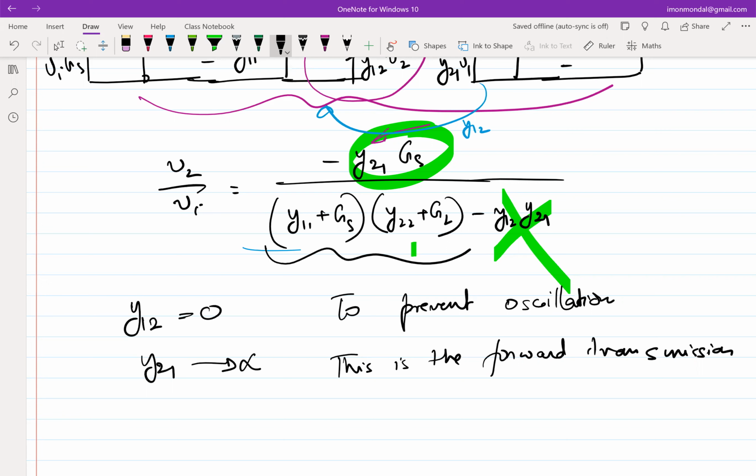Something tending to infinity and something being set to infinity are different things. Because if something is set to infinity, then when you're putting it in feedback, there can be a likelihood of self-sustenance. That is what we demonstrated, right? So if this term goes to absolute 0, not tending to 0, then there is self-sustenance. But if something is going to infinity, but not fully to infinity, we have not hit that self-sustenance.